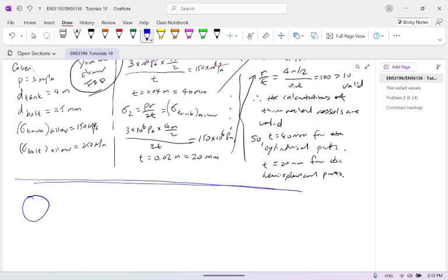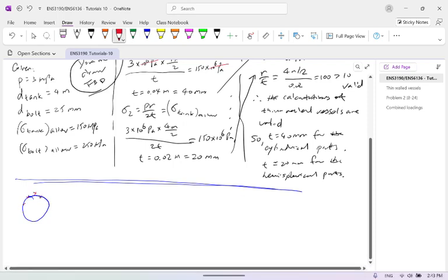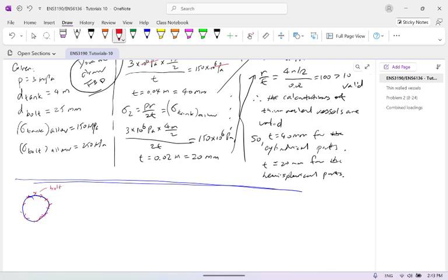So of course, each part is fixed by bolts. Clear? Put bang, bang, bang together. So from here we can get an idea of this. This operation is quite simple, but we should work out how much each bolt can sustain. That's why for this I use different colors to show you. So for each bolt, you can see the P bolt allowable, the maximum value, should equal to the sigma bolt times area.